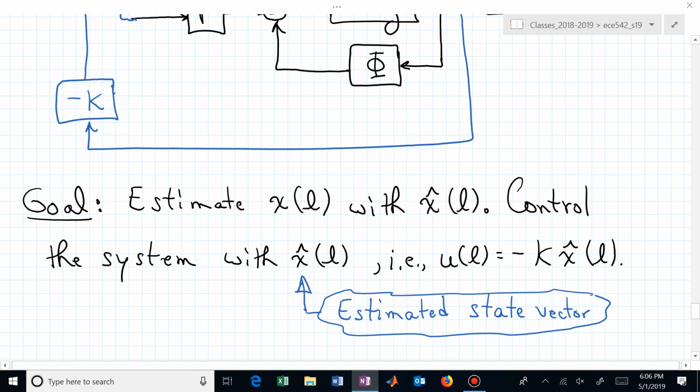Question? So, I guess the idea is you're trying to come up with an estimation of your state and use that to actually drive the system, right? How much faster does your observer or estimator need to be to give you enough time to drive the error to zero? The question was, in a nutshell, how do we select L sub p? How do we select our estimator gain to make our observer? You're going to hear this many different ways.